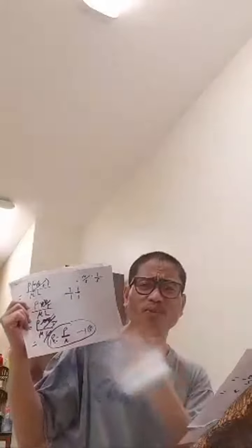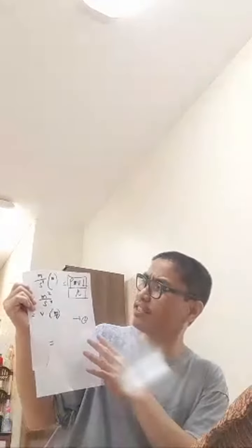It looks strange or unfamiliar or unusual. But here, it looks familiar and common. Density times velocity times length over mu. So, this is going to be the formula of Reynolds number. Viscosity is in the denominator, and the numerator is the inertial force. The inertial force depends on the velocity. Otherwise, it's not an inertial force, just density. It doesn't make sense. Velocity is the gradient in momentum transfer.